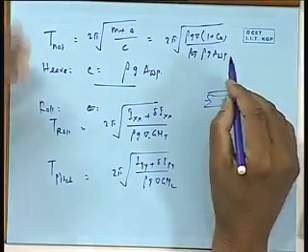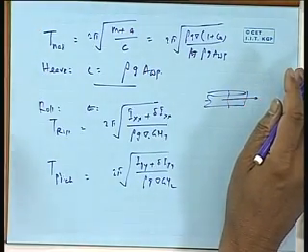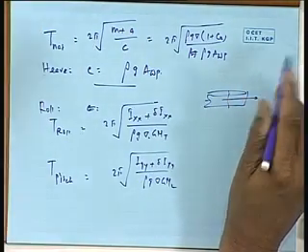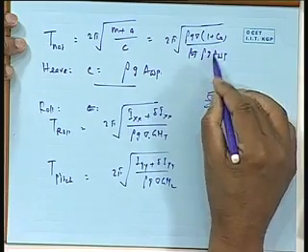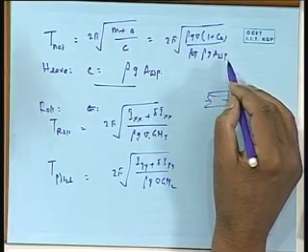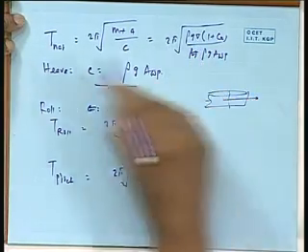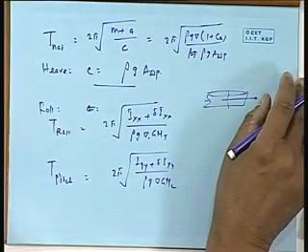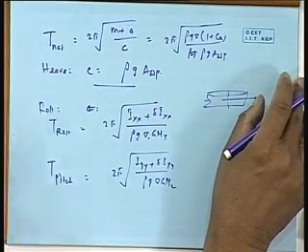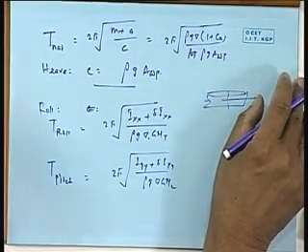Now, yesterday I mentioned, and we will do that in our assignment, that if you have A_WP high compared to the displacement, then this becomes small. In fact, for a typical barge it becomes 6 to 8 seconds, for a ship maybe 12 to 14 seconds, for a semi-submersible much more. This is how these numbers come out. We should have a feel for the numbers.